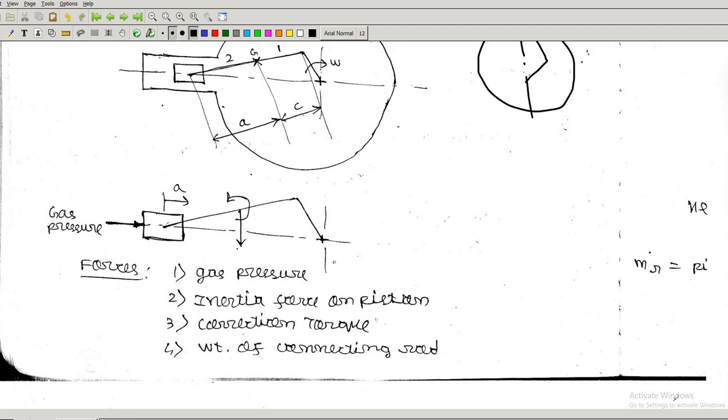As we have seen in our previous lecture, the connecting rod is executing general plane motion, but we'll divide it in two parts. One part executes pure linear motion along a line, and the other part rotates about the axis as a particle placed at the crank tip.